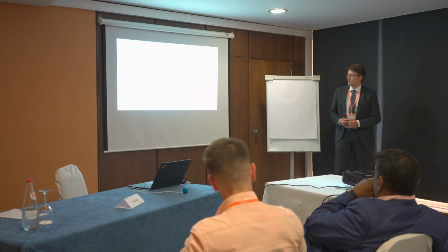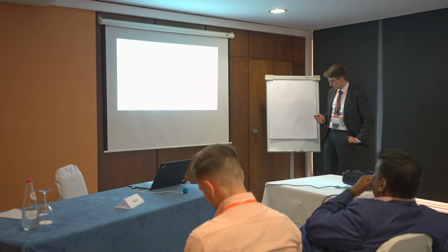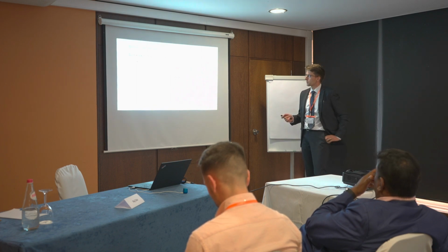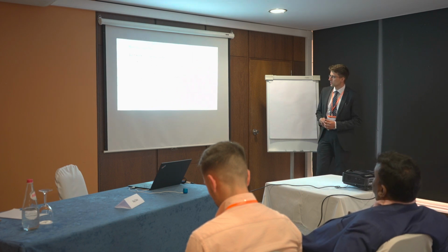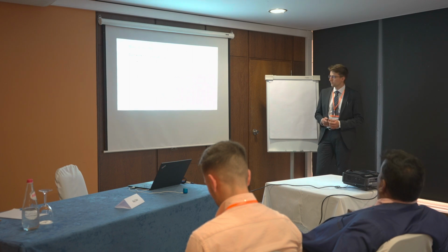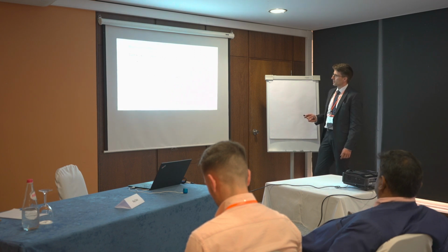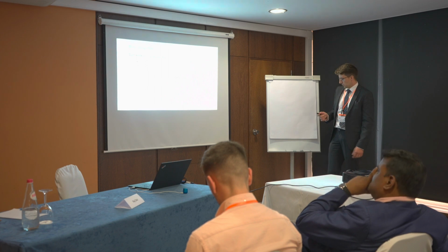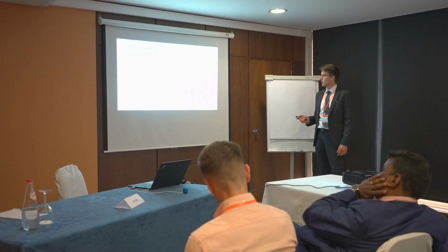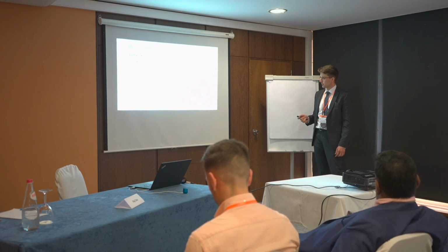So let's have a look at the drawing of this Kolsky bar setup. We have the striker bar, which is propelled by compressed air. The velocity of the striker is measured by two light barriers. One of them is used as a trigger for the data acquisition system. The striker bar hits an incident bar, and between the incident bar and the transmitted bar there is a specimen, in this case a compressive specimen. Then we also have an optical extensometer, which measures the displacement of these two interfaces, 1 and 2.